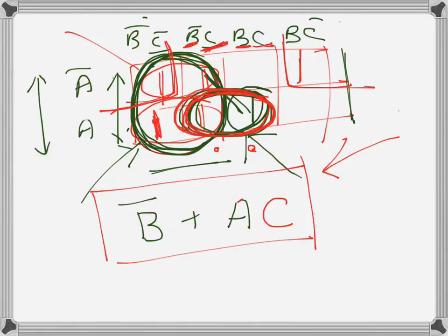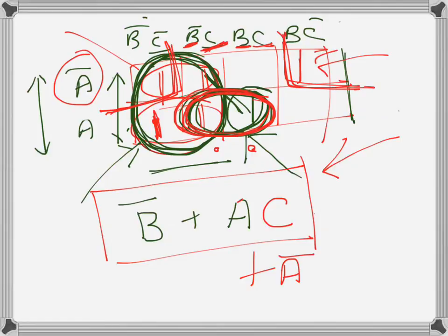So for the expression, let's assume this one is also there. Again I can see A bar is not changing, so that would give A bar if this one was also present in the K-map. And here what is not changing is C bar. We can see C bar is the same because B is changing: here it is B, here it is B bar, so no B term but C bar. So yeah, it's just like that.